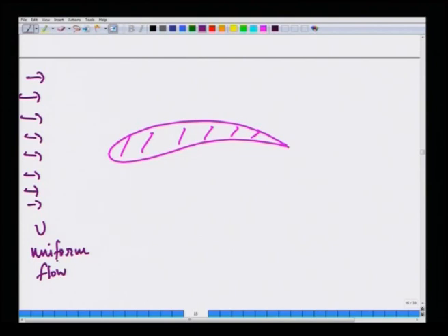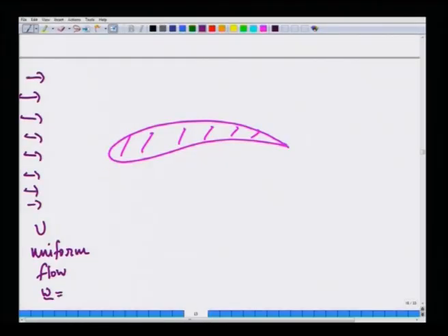It is a kinematic feature of a uniform flow. If you have a uniform flow, regardless of whether you consider the fluid to be viscous or the ideal inviscid fluid, if you merely compute the vorticity, since there are no gradients in the flow, the vorticity has to be identically 0. So, there is no vorticity when the fluid is flowing far away from the airfoil.